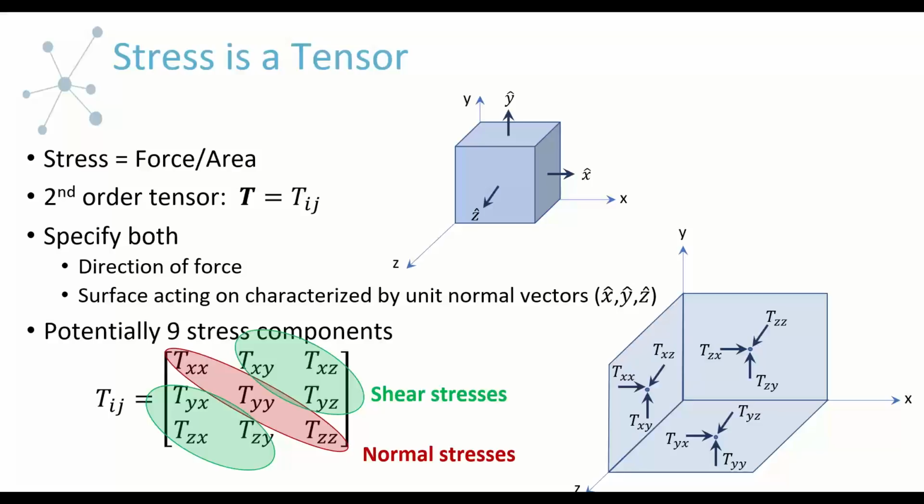And it's more specifically a normal stress difference, because you need a difference in the normal stresses to actually generate a deformation. If all normal stresses are equal, this is like atmospheric pressure, an isotropic normal stress, and it doesn't lead to deformation. So to take it a step further, we're actually going to be talking about a normal stress difference.